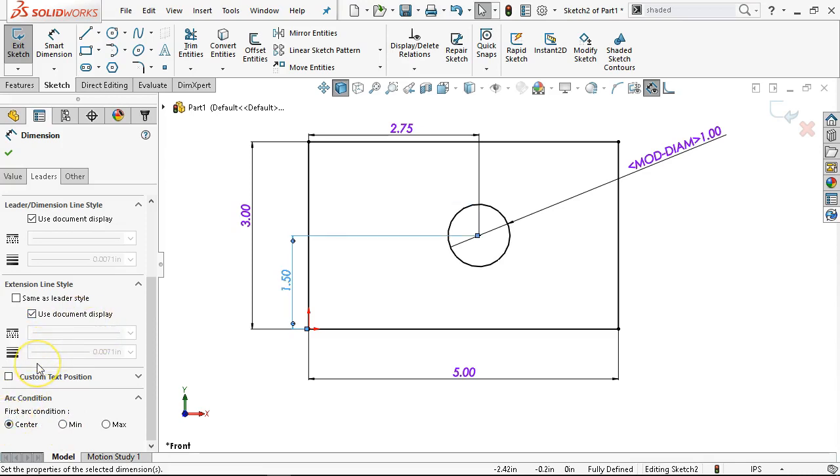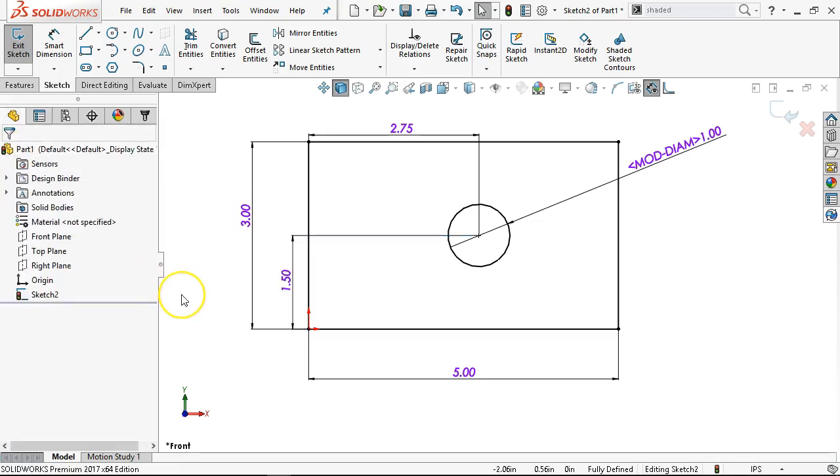All right? And so if I'm reverse engineering, if I have this part and I want to do a dimension from the bottom edge of the circle to the outside edge, and I pick the center point, I have to do math. I don't want to do math. I have this great tool that says if I pick the circumference, if I pick the perimeter, it will do the math for me. I can take a direct measurement, I can enter it as a value, and it will show me the distance from that edge to that edge.